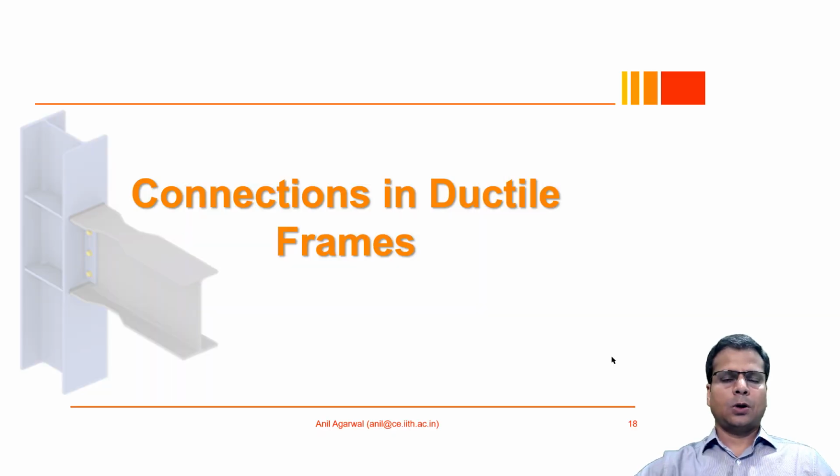So in this lecture, we will talk about connections in ductile frames. We require ductile frames, especially in seismic conditions. When we design a structure for seismic loading conditions, the seismic loads are typically so high and they exert such a large force demand on the structures that it is unreasonable to design them for elastic behavior.